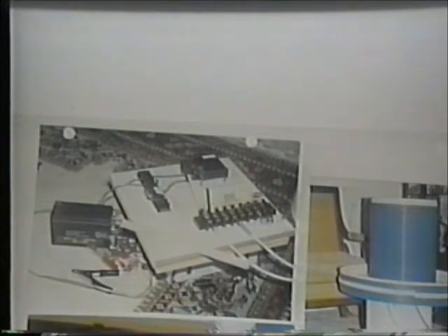What you're looking at here is an automobile ignition coil. Where the 12-volt electricity comes in on that connector block, basically I've used a timing circuit which is very common. You take a capacitor with a resistor shunt across the legs of the electrolytic capacitor, and you run electricity through it. You're going to end up with a timing deal. It's going to be cutting it off and on. So it's the resistance times the capacitance of the capacitor that tells you how many times per second this particular ignition coil is coming off and on.